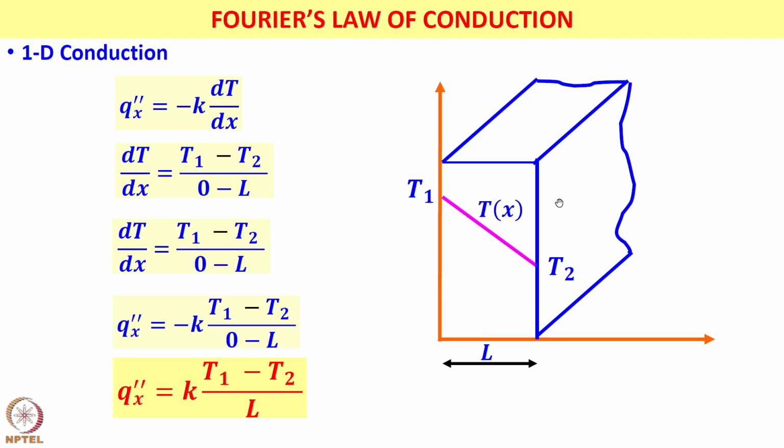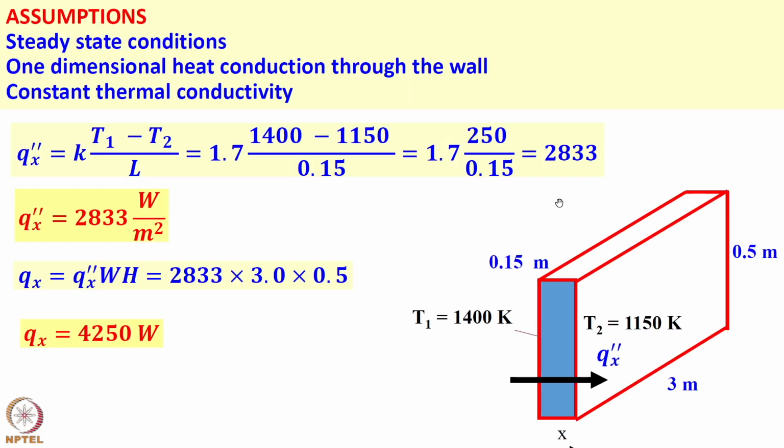So you take a wall, outside wall of the house is a plane wall. So this wall has a finite thickness, the area is A. Q divided by A, both sides the area is constant. At every plane inside the wall the area is the same. So Q divided by a constant is heat flux, watt per meter squared. dT by dx we have shown. So Q double prime is K into delta T by L. I'll come back to this problem.